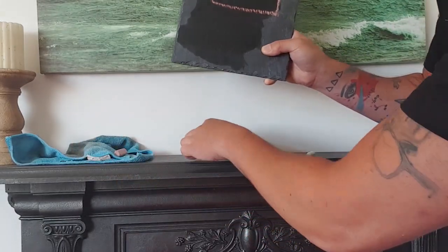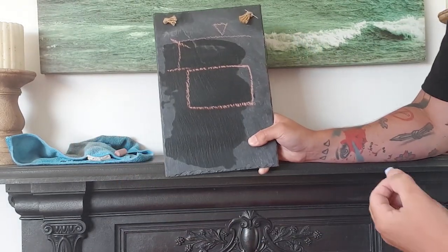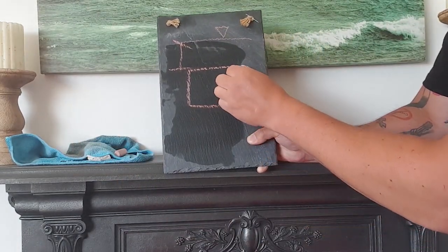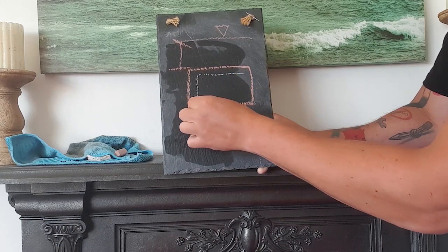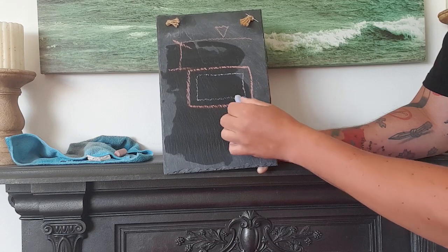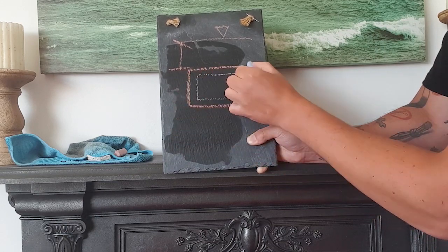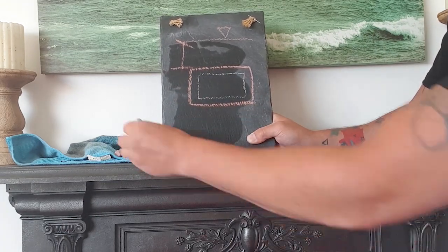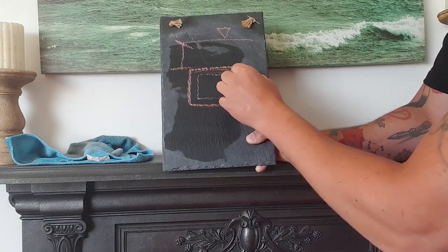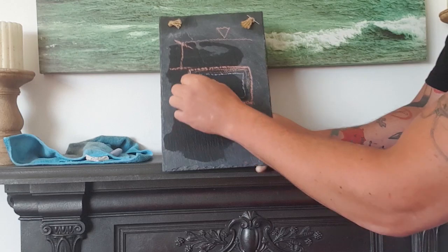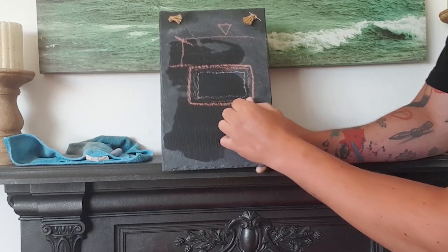So when I talk about cover for foundations and the rebar, I'm talking about like an invisible cover that comes 50 mil or 25 to 50 mil from the outside face of the foundation. Now this cover area is an area that shouldn't have any rebar inside it.